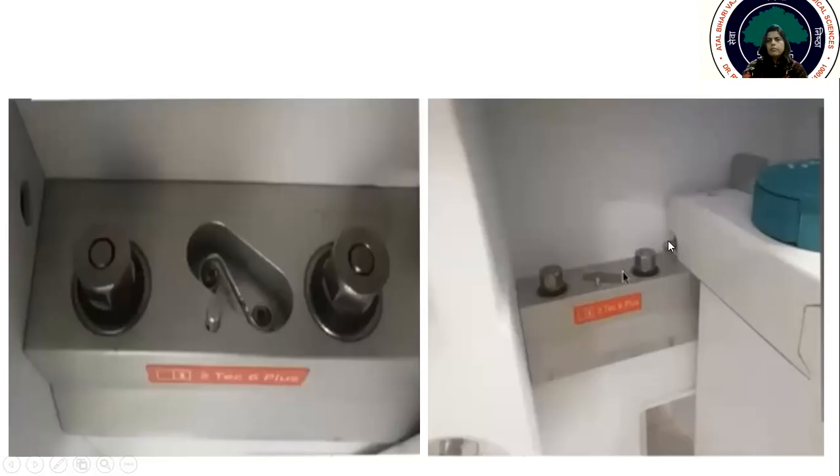Once you switch on the dial, this lateral rod will move laterally, and it will block the adjacent vaporizer, so that the adjacent vaporizer cannot be opened until this one is closed. Only then can the adjacent vaporizer be opened.